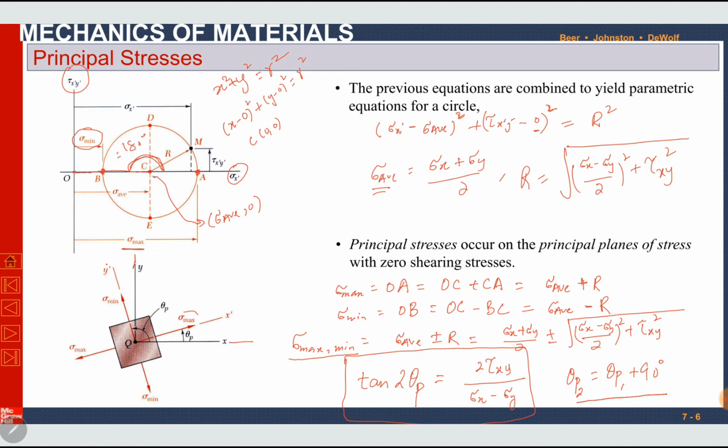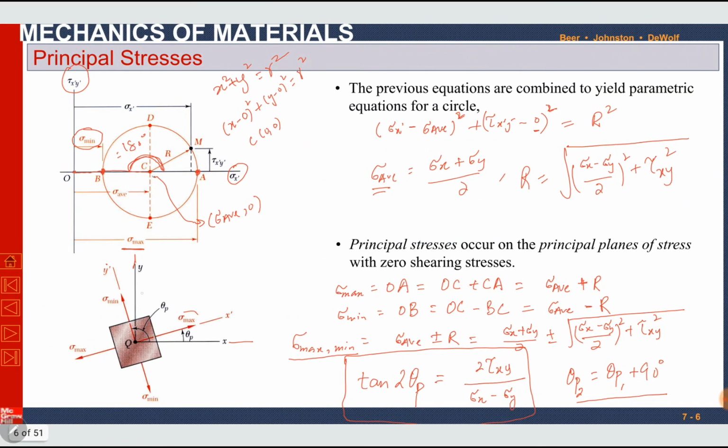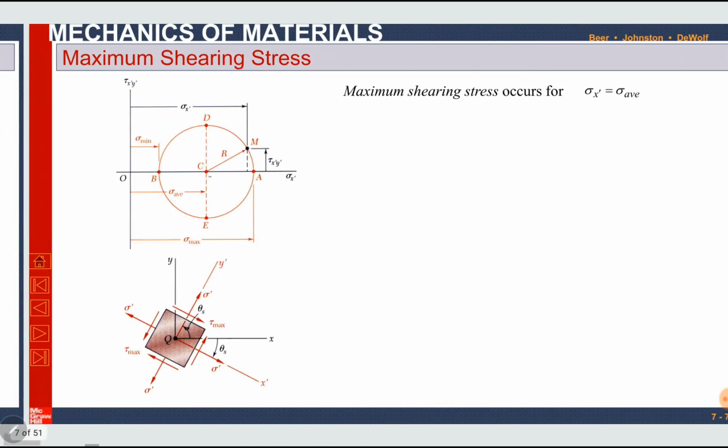Okay, again, whether this rotation should be clockwise or counterclockwise, we can use a sign convention. Here in this book we are using a sign convention of positive for counterclockwise direction and negative for clockwise direction. When you draw the Mohr circle by yourself, you can see graphically if the angle is clockwise or counterclockwise, but while using formulas you can use this convention, positive for counterclockwise and negative for clockwise.